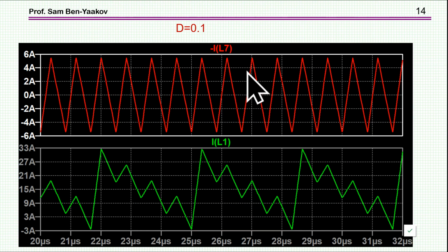However, if the duty cycle is not 0.25 or 0.5 or 0.75, because in all these singular points of the duty cycle we're going to have 0, then if it is not, like it is 0.1, then I'm going to have quite a bit of ripple, which is now being added to the primary, since it is reflected to the primary, and here is the waveform that I'm expecting now at the primary. Now this is for one phase. I have 4 phases here, which are shifted, and all are summed up, and of course fed to the output. Okay, so this is really what happens.